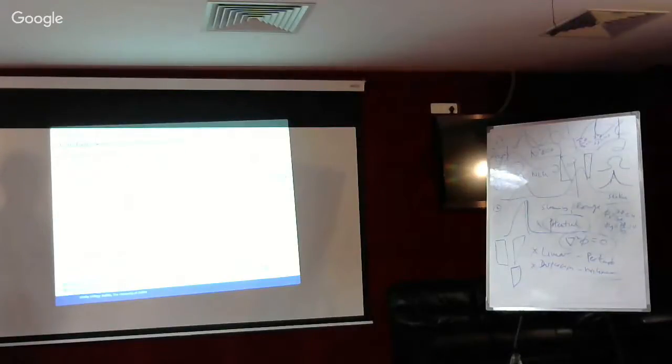And in this case, we again compute the wave elevation by using this sine cosine function, and the fluid velocities and accelerations are obtained by using this expression, very similar to what we had previously, the same way, except that the amplitudes are modified by the term omega minus Uk. So in this case, obviously, it can be positive or negative. That will actually change your overall response.